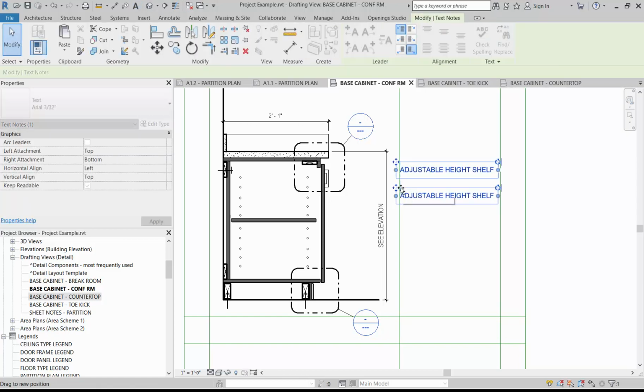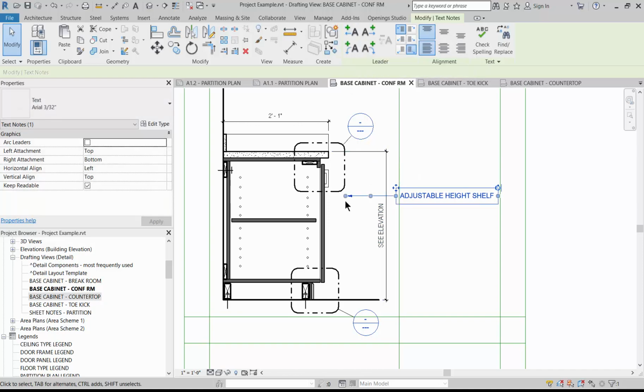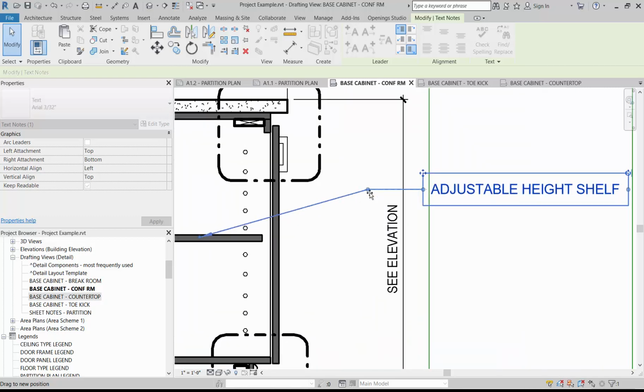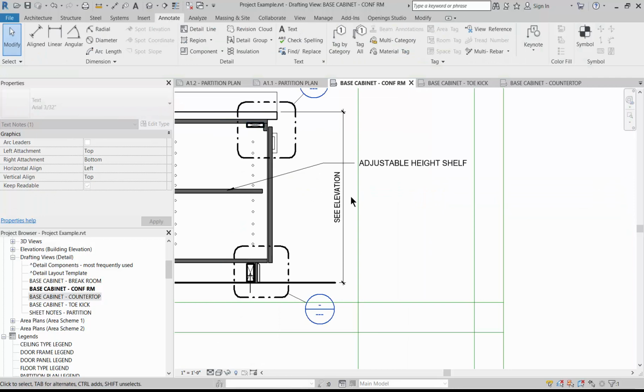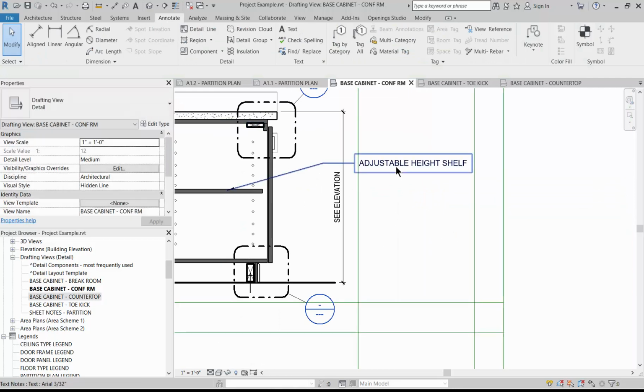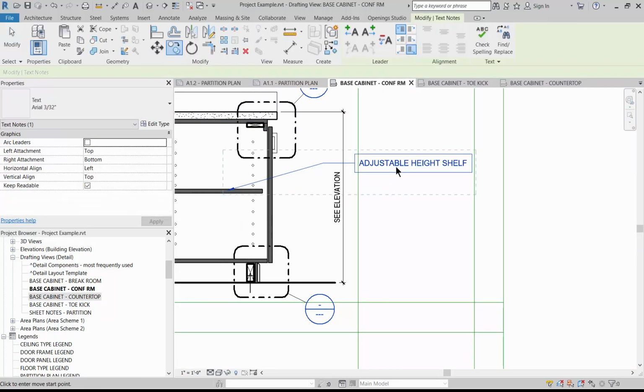I'm going to locate that, be very careful not to overlap any dimensions, and then add a leader line with an arrow, same 15-degree filled arrow. And then the only thing I would make sure to add that you show is that you line up all of the nodes.